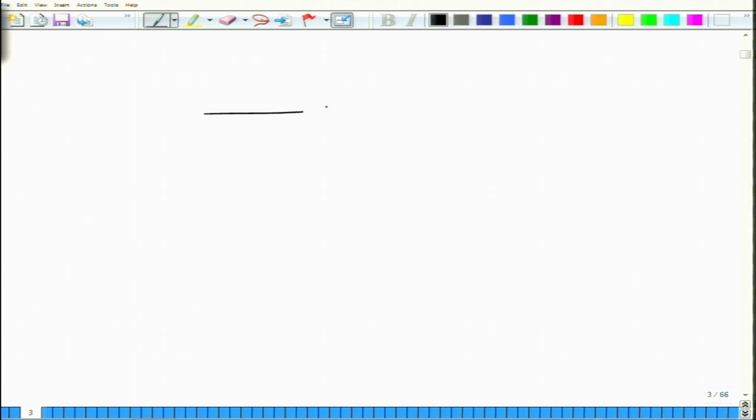Suppose I have some conduction band and I want to fill a certain energy band delta EC. So EC plus delta EC is the next range. I want to fill this entire range of delta EC above the conduction band with electrons. So I need to know how many electrons are necessary. Let me put a small e to indicate that I am going to fill this region from EC to EC plus delta EC by electrons. So what is the number of electrons that I require?